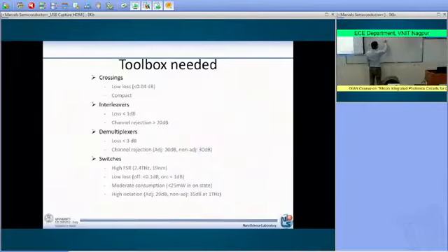However, if my resonance is this one, and this one, and so this is the free spectral range, you see that while I'm moving this resonance here, also that resonance is moving. But this resonance is moving in a wavelength region where I have lambda 12. And therefore it happens that the same microring is routing this lambda 1, but is also affecting the routing of lambda 12. And I want to avoid this.